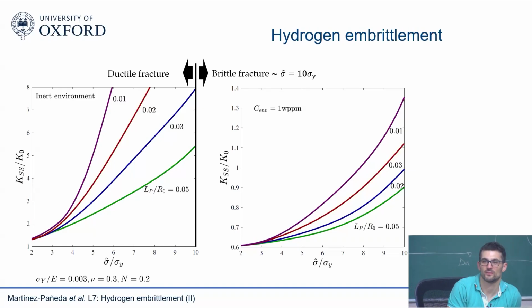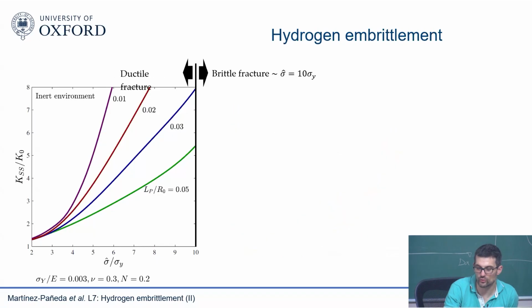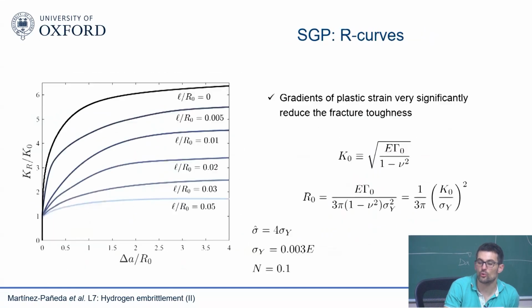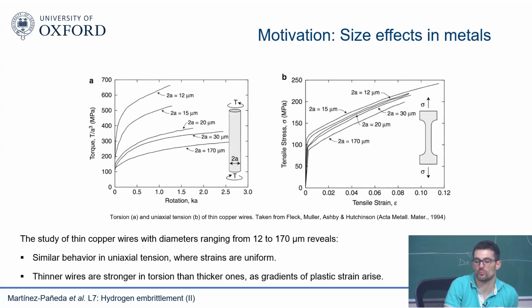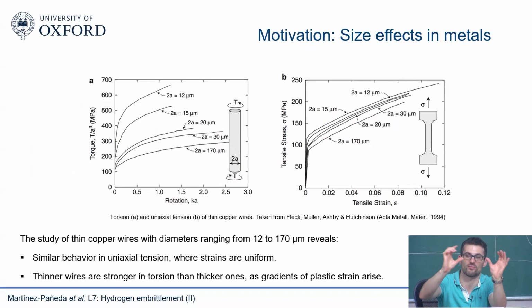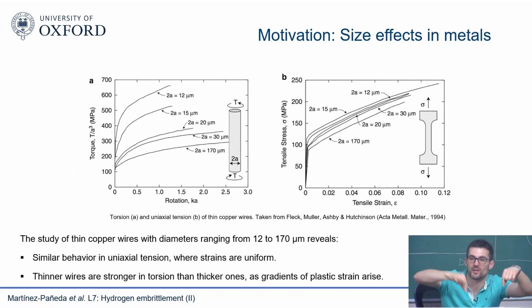The hardening due to the lower length, meaning the small L, was not there for the uniaxial test only? Yeah, because the uniaxial test has no gradients of plastic deformation. The stresses are uniform, so there's no non-homogeneous plastic deformation. It's all uniform. You need the gradients, you need the spatial variation of plastic strains to see this GND effect. So GNDs are dislocations that need to be geometrically necessarily accommodated. So you need to have a gradient of plastic deformation to fix them in. Otherwise, they don't exist.